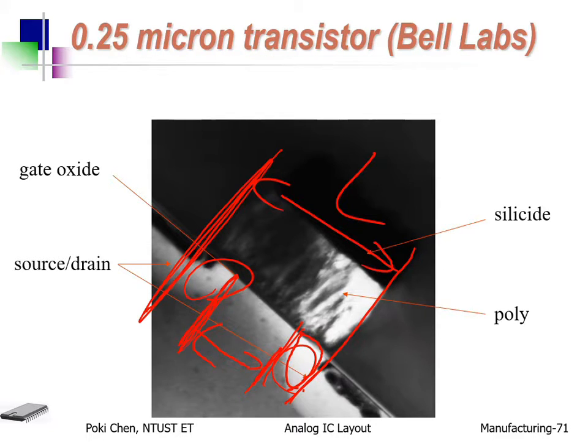How can I say much shorter? According to diffusion, it is shorter than the length you draw during layout. For implantation, a little bit less, a little bit shorter than the length you draw. That's it. You need to keep this in mind.